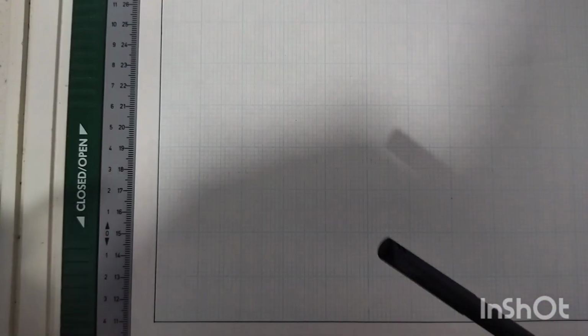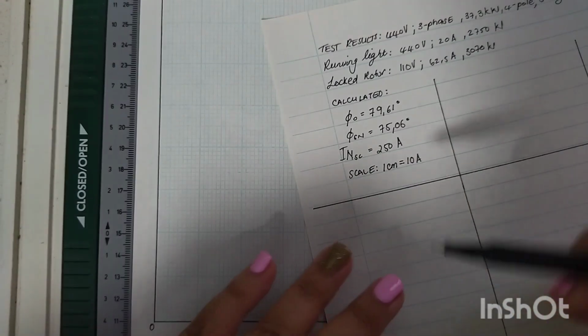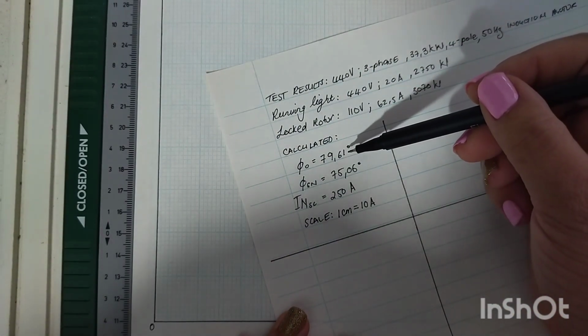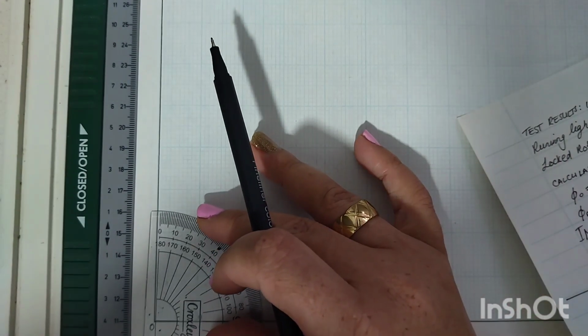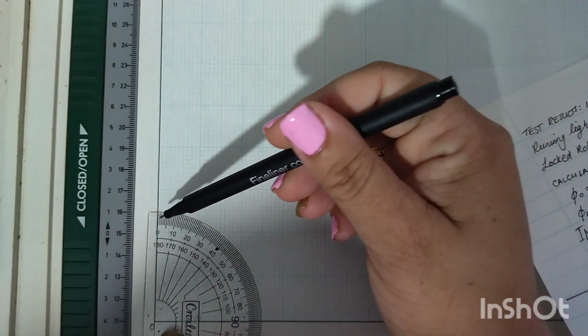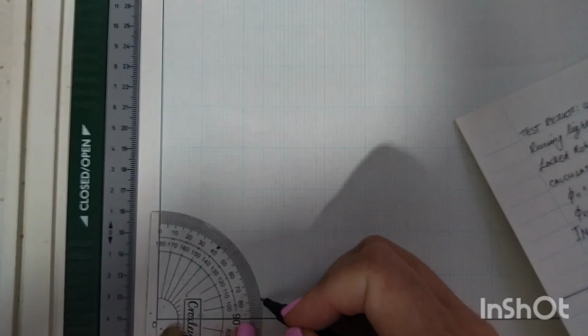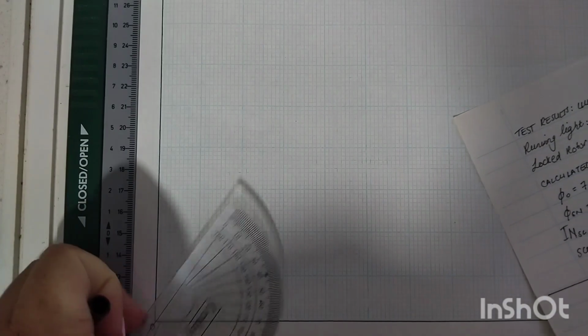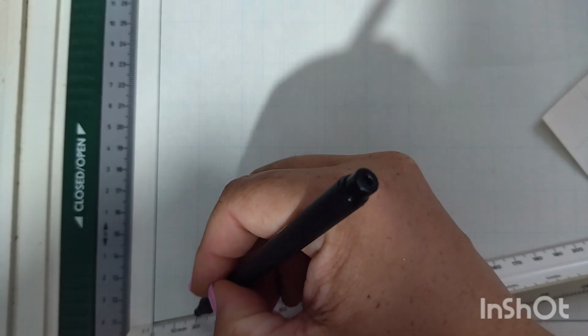So the first line you're going to construct is, with this being your 0 point, of course, your no load current, the 2 centimeter line. And for that, just a reminder, our angle is about 80 degrees. This angle is measured from your vertical axis. So if I'm going to place my protractor over there at the origin, I'm just going to measure about 80 degrees over there. What's 79.6? So yes, it's going to be about 80. I'm just going to make a dot to mark that position, because that line from your 0 point is only 2 centimeters. So using from 0 to there as a guide, I'm going to mark out 2 centimeters, only 2 centimeters.